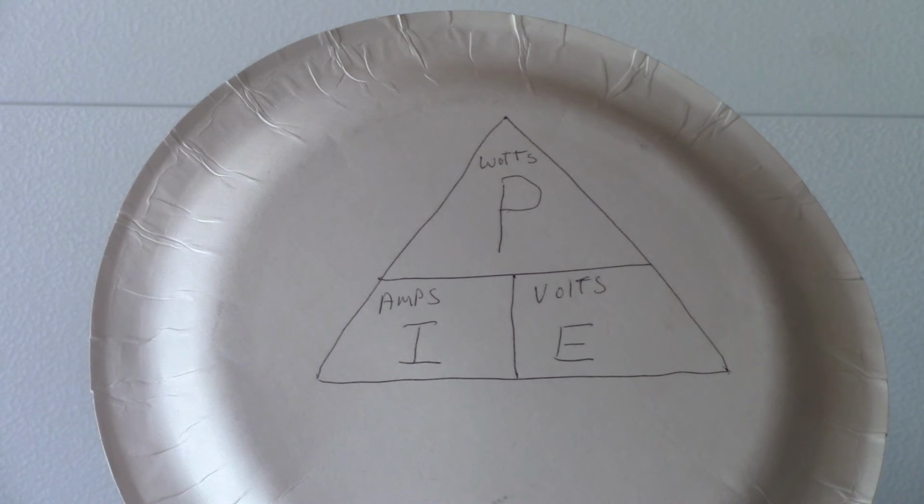They would have been better off buying a higher quality, larger system to start with, or a larger charge controller, for instance. Then as they progressed up in inverter size, that charge controller would be able to go with the inverter. So knowing Watt's Law and your future goals can help you determine, okay, maybe I do want to buy this bigger charge controller up front, and buy more batteries as I go along. All of this stuff is very important.